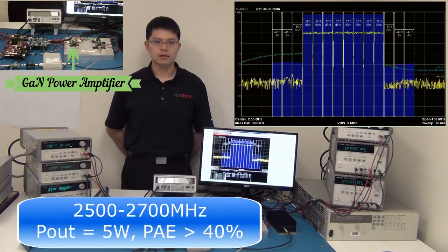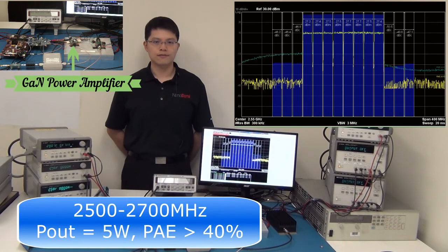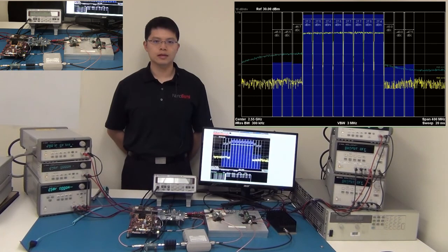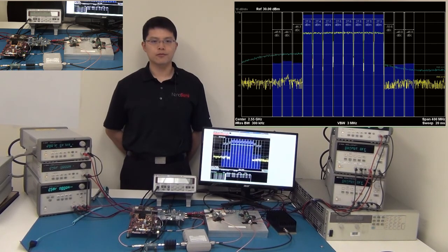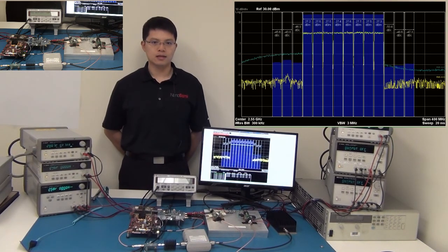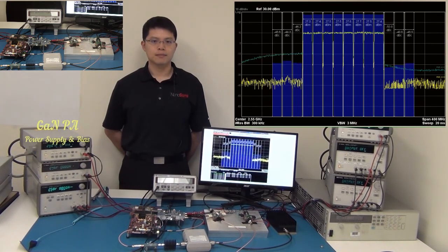The first part highlights an integrated two-stage gallium nitride power amplifier designed for metro cell base station application with a target 5 watts average power at the device output. It incorporates a Doherty final stage, delivering more than 40% power added efficiency with a gain of 36 dB. This module is 50 ohm input-output matched and is compact in a 36-pin 6x10 mm plastic surface mount package.